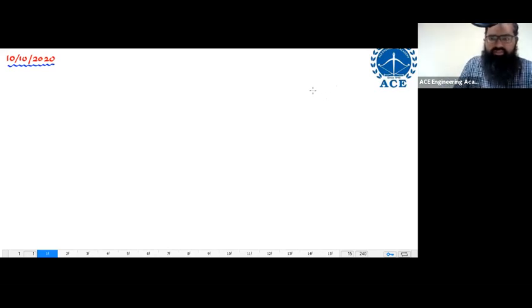So this particular slide is the revision of yesterday's class. Very important slide. The first thing you have seen in the concept of flow through pipes is that whenever you have a steady and fully developed flow, you have some equations valid for every flow, regardless of what Reynolds number you have. Now, what are these equations? The first equation is the governing equation, which says that R into minus dP upon dx is equal to d upon dr of r times tau. This was the first point we discussed.